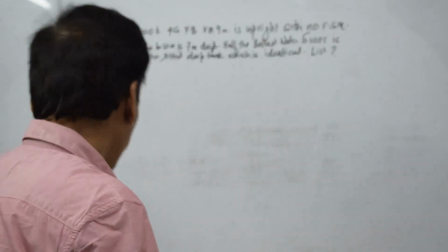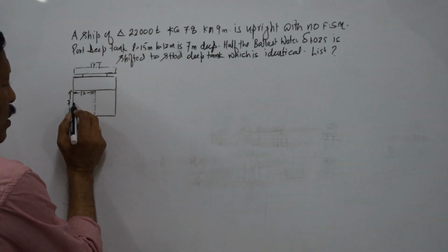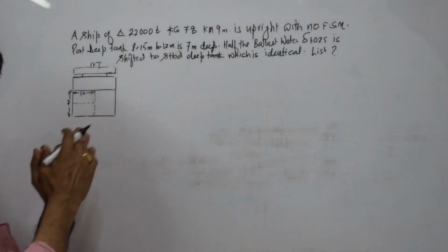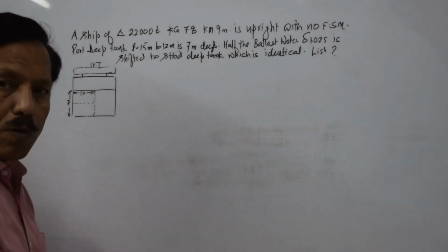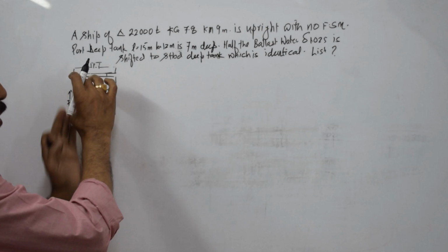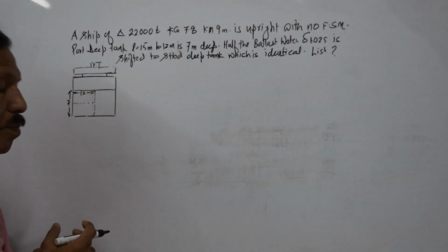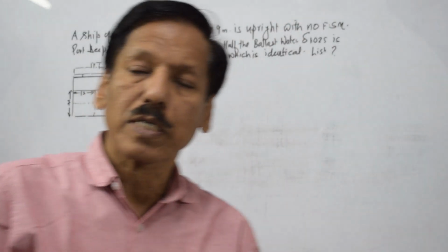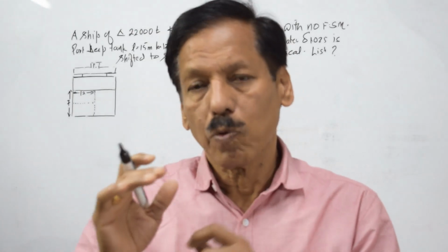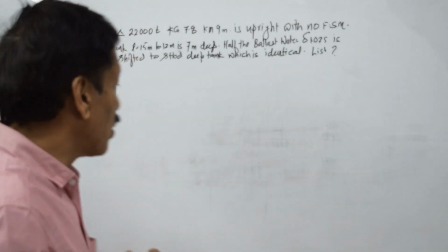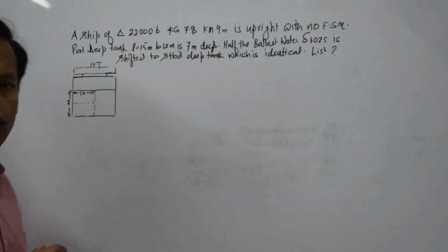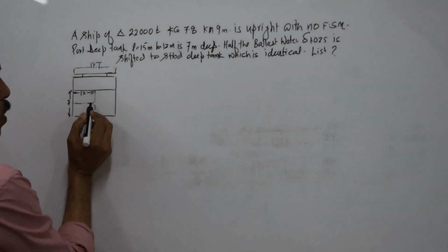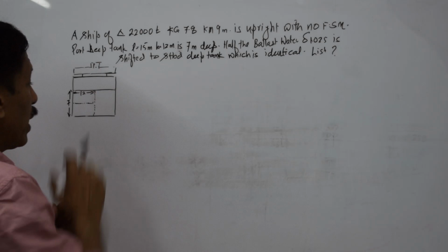One way of doing the calculations is as if this 50% block of salt water, the ballast water, is pumped out of the ship, and the same block of ballast water is loaded in this tank. That is one way of thinking of it. So in the KG by moment calculation, in one step we pump out this liquid, and in another step we load the water here. But let us say, instead of pumping out, this half block is directly shifted here.